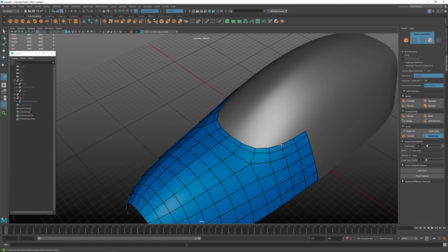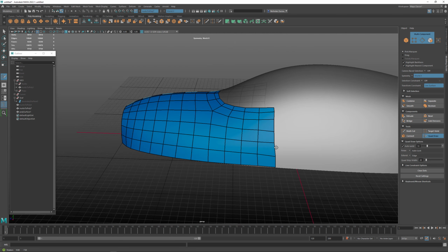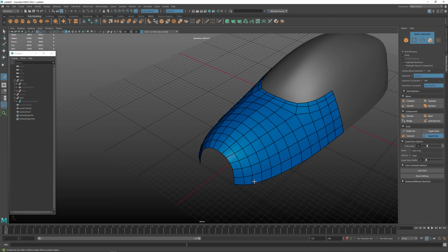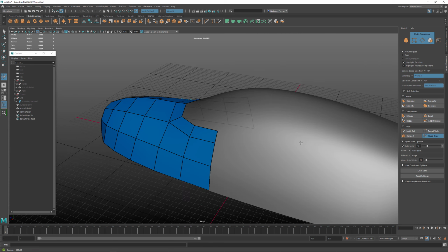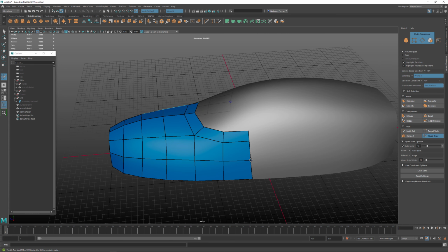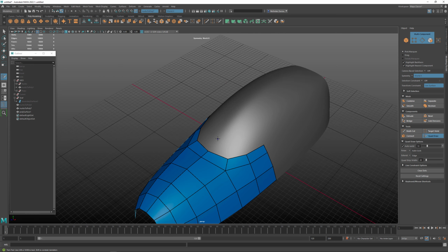So here we go with this surface, and again, if I've gone too complex with this already, which I really don't need this much geometry at the beginning, we can hold down Control and Shift, and then we can get rid of these loops that we placed within here. So we can simplify the geometry like that. And again, my personal opinion is to work at a lower resolution at the very beginning. Let the computer do as much work as possible for you.